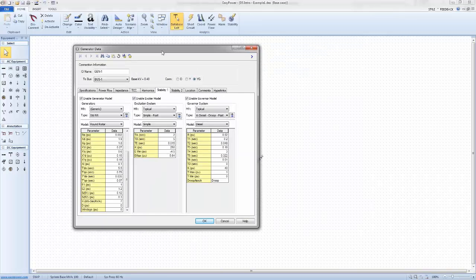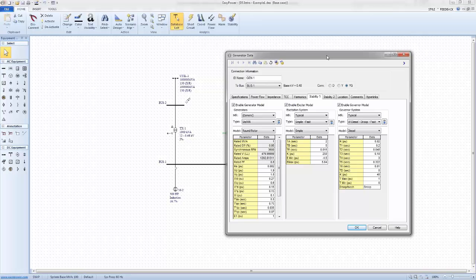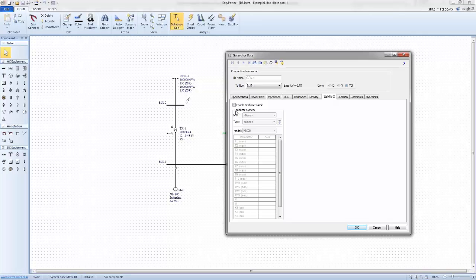It is a synchronous generator here, but we use a DQ model for both of them, in general for induction and synchronous machines. And you can see all these parameters. Again, I have to really emphasize that there is a lot of information here, and if you're interested in a precise response of voltage or currents of a system, that's the way to go. You should start putting these values in your dynamic stability module, simulate it, and look at the results. We don't have a PSS here, so I'm not going to activate that one.